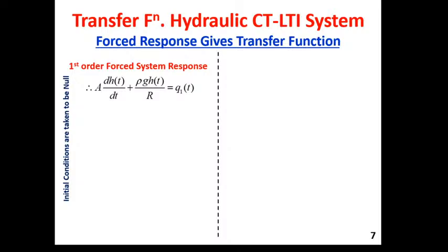So this slide is about finding the transfer function; the previous slide was about finding the system model as an ordinary differential equation. How do we find the transfer function? Take the Laplace transform on both sides, so dh(t)/dt becomes sH(s). As was told yesterday, in the time domain the parameter is given in small letters, so h(t), but whenever we are in the Laplace domain it is given in capital, so H(s), H is capital.